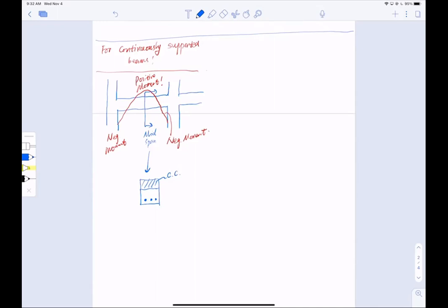However, for the negative section, you do not have that anymore. Your compressive zone is at the bottom. The tensile reinforcement you saw becomes compressive reinforcement, and the compressive reinforcement becomes tensile reinforcement. What does it mean? It means I have to compute them differently. It looks like the same section, but when I compute my moment of inertia, I have to compute them separately.